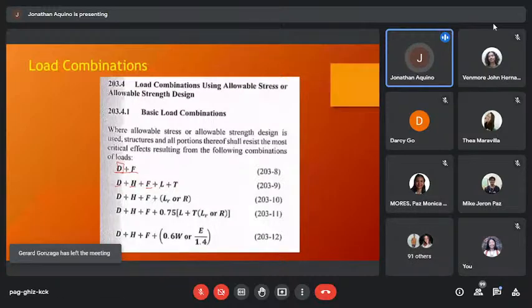For design, normally the present loads are only dead load and live load. There is a temperature load, but this is very small compared to the other loading. So to simplify, in the beam design or flexural design, just simply dead load plus live load. But of course, if you have hydrostatic pressure, like a basement beam, you need to consider the hydrostatic pressure.